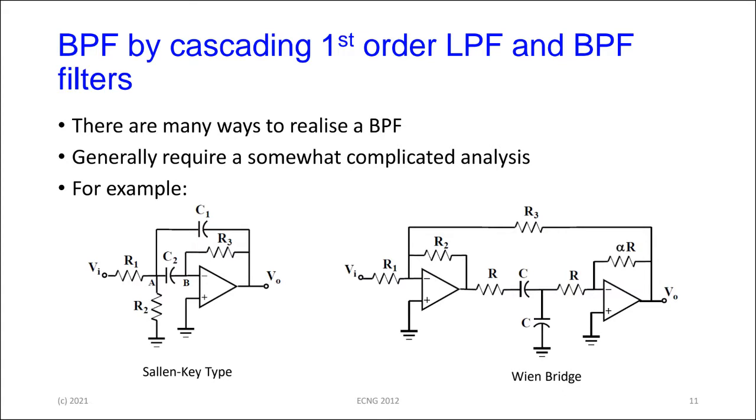There's a version here. Now, you still have the two capacitors, but you have an extra resistor inside of here. And depending on the behavior, you will notice that C1 and R3 may or may not be in parallel, depending on what is happening with C2. That's on that side. And then on the right-hand side, we have one that is based on the Wien bridge.